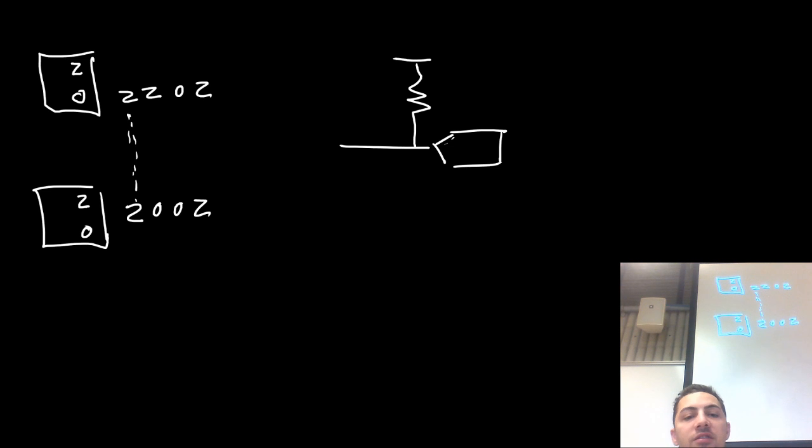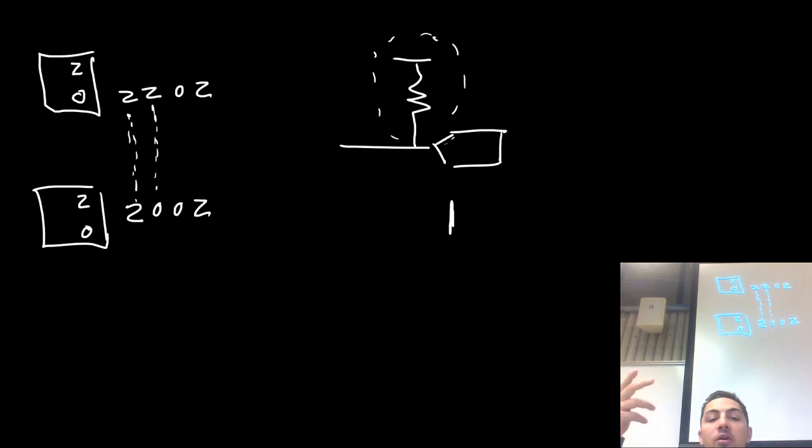Well, no. Z appears here, but when you add in this thing, well, logical 1, yeah, 5 volts. Becomes a logical 1. What about when we take Z and 0? It's a 0. The Z lets go of the balloon, but the 0 is still holding onto that balloon, so it stays low. Now, what happens when both of them are 0? Is there any conflict there? No, they're just both holding onto the balloon. It's at the same state, so it's a 0.